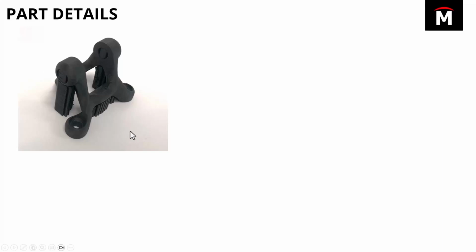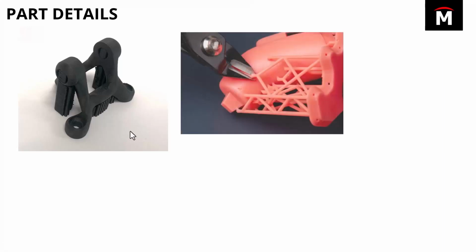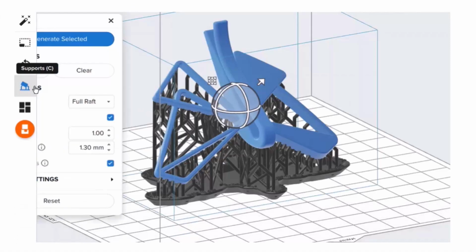And also support material sometimes can affect the dimensional accuracy of the part, which with SLA printers, with the truss style supports, having to snip those off, you're going to have to sand that down because those pips are going to obviously affect the dimensional accuracy of the part, which can be one of those things you can control in the slicer.